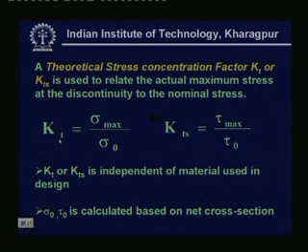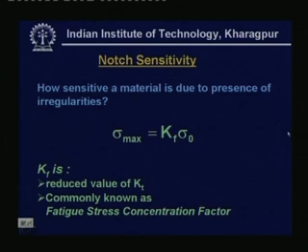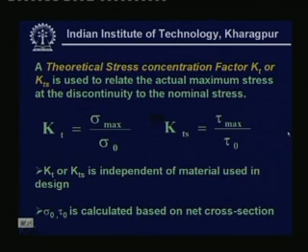So, we define Kt equal to sigma max by sigma 0, and Kts in a similar manner as tau max by tau 0, where sigma 0 and tau 0 are the stresses which we define as the nominal stress.